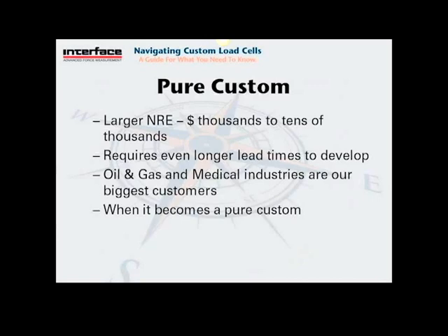So that's one type. And the other type that we do is load cell or torque transducer modifications as well. Those are the ones where, let's say, the thread size is larger than the standard flexure can take, so it has to go fully through the engineering process, or if it's a custom load cell that's never been built before, that'll go fully through the engineering process.